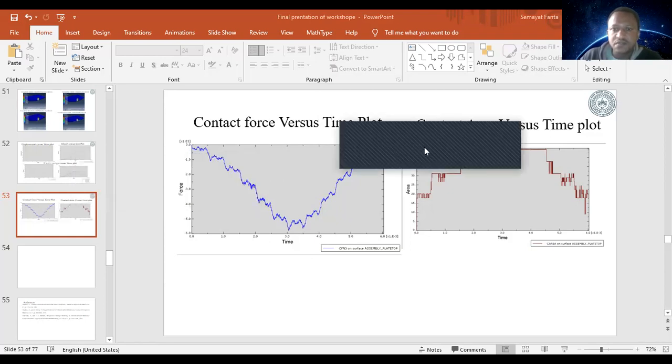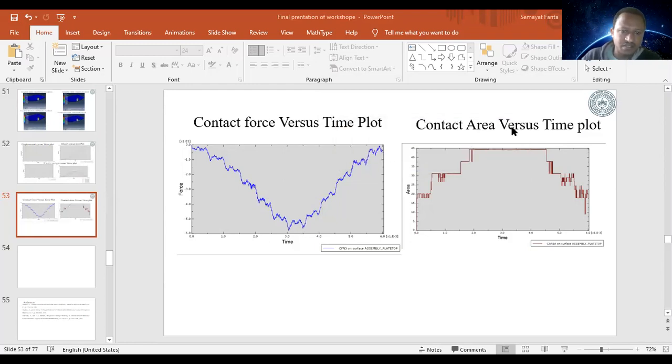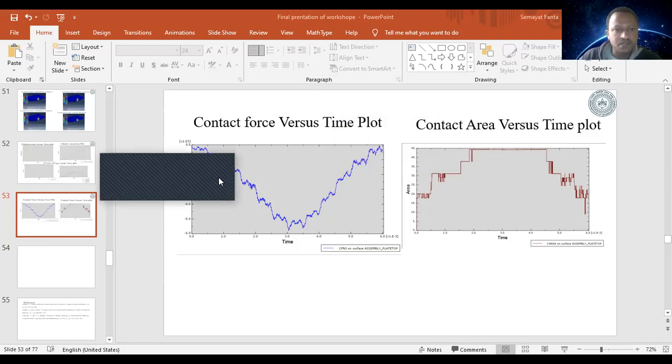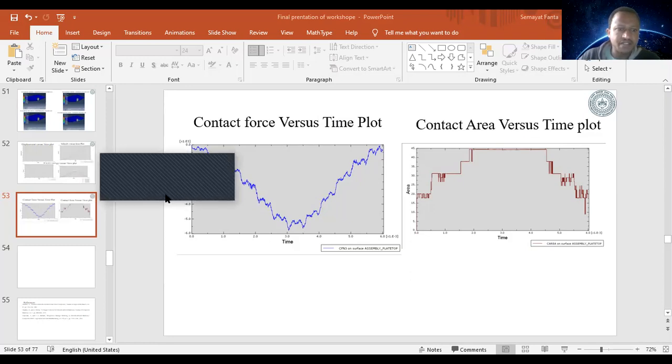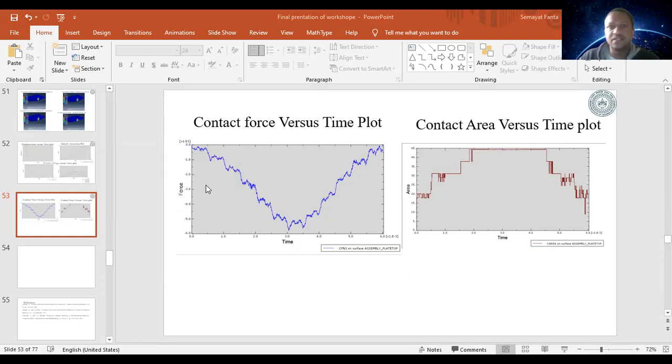The user subroutine file must have a .for extension because of my system, but a system with a proper Intel Fortran compiler can work with simply the .f extension. So for that reason, let me